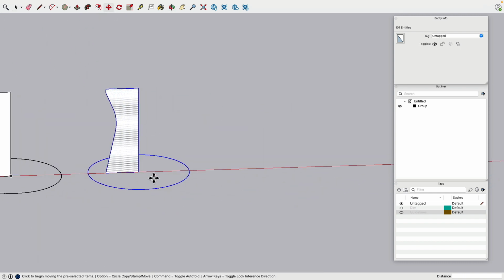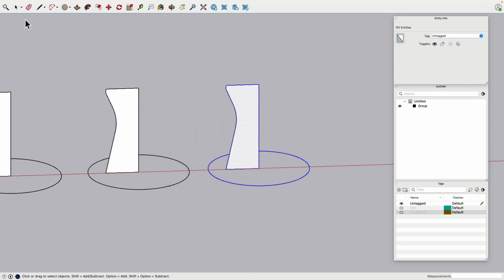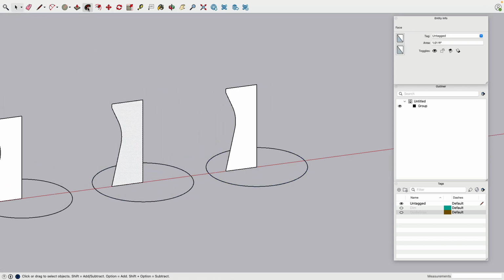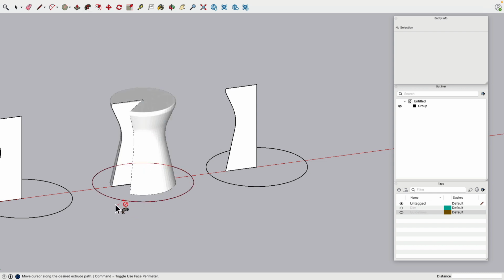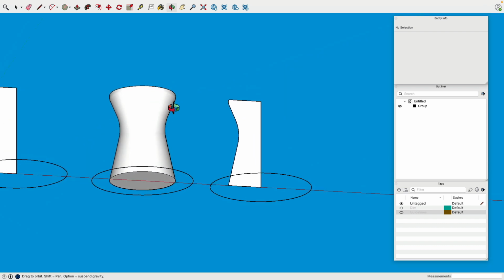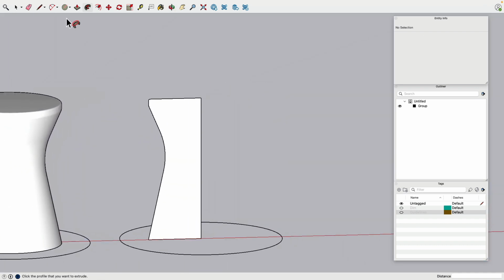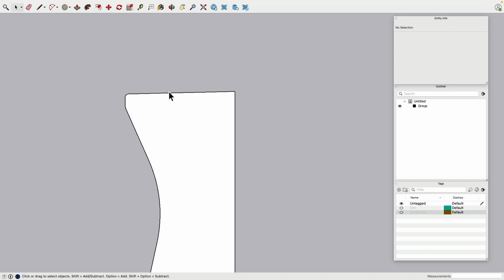But let's make a copy of all this first. Let's go to here and I make myself another copy because there's another design idea I would like to make. Okay, now it looks quite good. How does this look when we have a little depression in there? Here again, the guideline can come in very useful. So maybe how deep is this along the z-axis. So I press the up arrow key, 0.5. Okay, and then from here over 0.7 inches. I meant 7 inches.